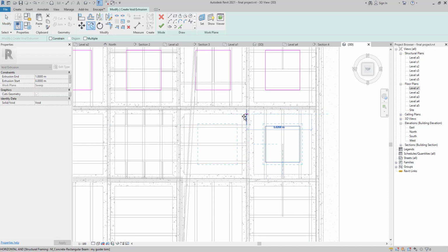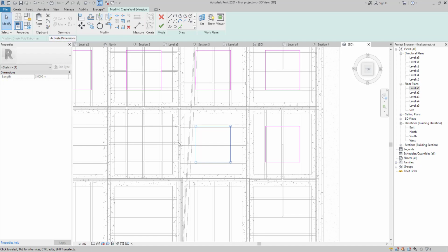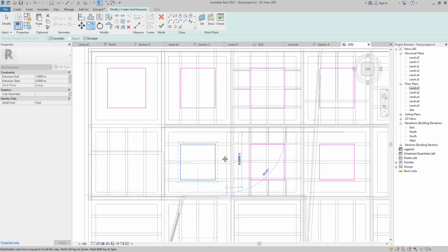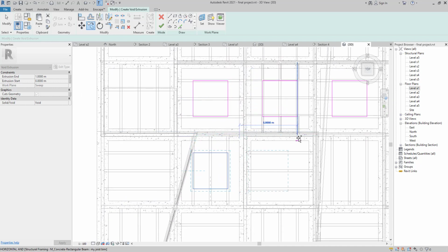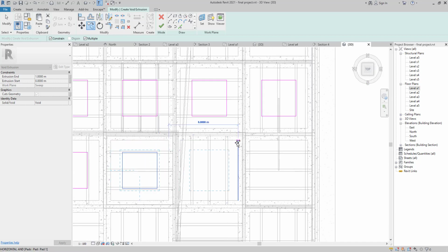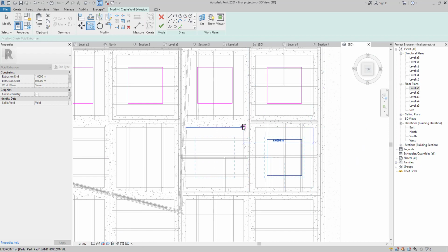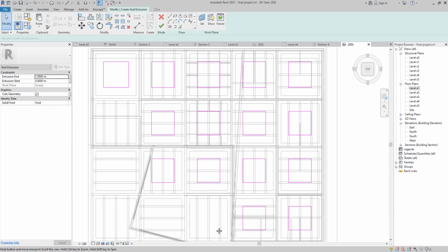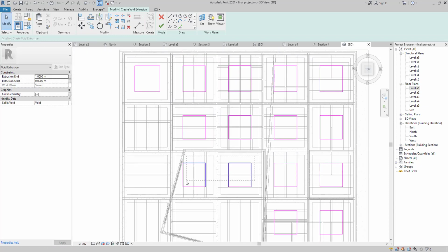Then here we can create one, and we can copy paste it because as you remember this size was the same, so we can just use the copy paste. Multiple even constraint is working here. Pick your point which you want to copy and use your copy tool. As you see, we are just copy horizontally and vertically. We are not moving around. It can help us to do our process faster, but we also should remember we do not need all of our boxes. For example, here it's not useful because as you see our wall is located here.